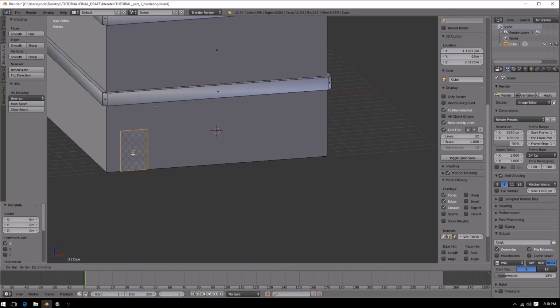Once you do that, without clicking or doing anything else, you can now move this plane anywhere you want. The duplicate plane will be moved anywhere you click. If you click an axis, so I want to move this on the X axis, if I hit X right after hitting Shift D, I can now move this duplicate perfectly on the X plane. So I'm going to move it right about here, and then move it up 1 or 2 units. Maybe right about there. Let's do right there.